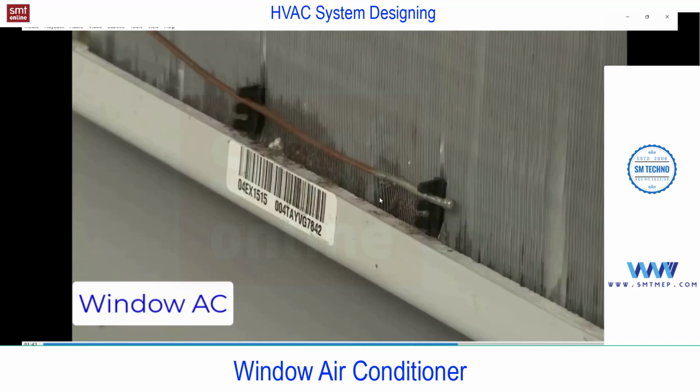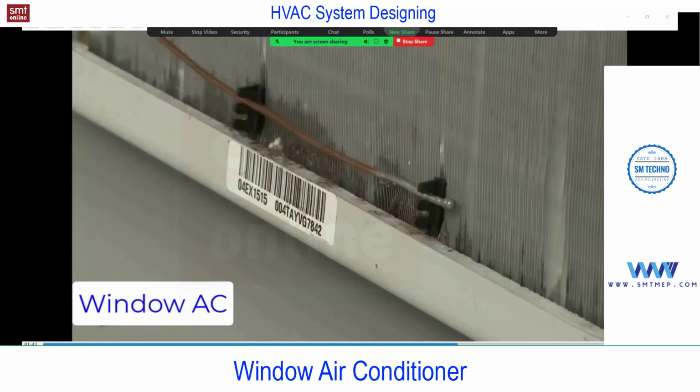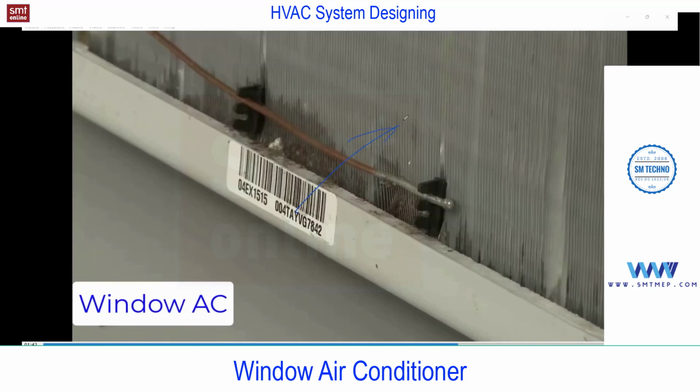So it means, you see, when the suction takes place, it will pass, one minute, it will pass through this, and you see these strips are fins, and in that you'll find the coil. So this is a cooling coil. So the suction from the room passes through this, and continuously this sensing bulb will monitor the return air temperature. Okay, and monitoring the return air temperature can control the compressor.